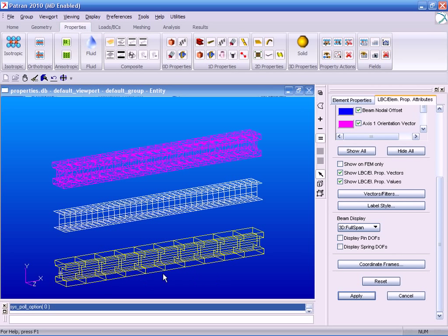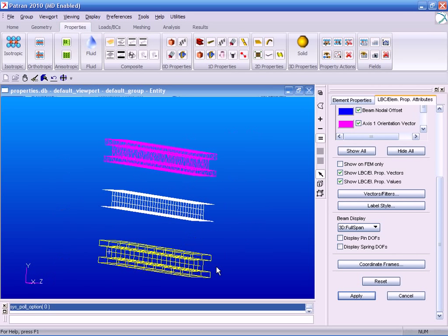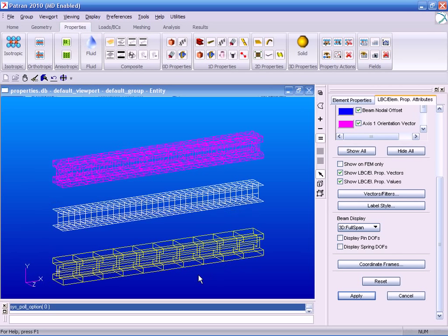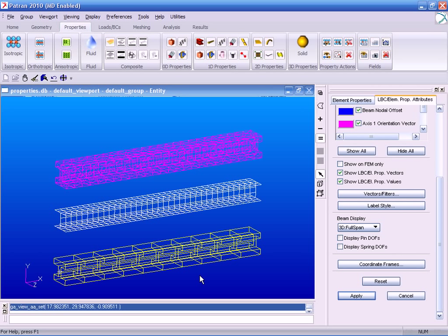So what we've done here is we've used the element properties, applying a constant cross-section to make up for the geometry information, or the spatial extent, that was missing from the elements themselves. And I can rotate the model and see that I did in fact get that beam orientation correct. If I'd used a different orientation vector, like say 1 unit in the z, this would be turned 90 degrees on its side and would obviously provide different behavior. So that's how you define your 1D element properties.